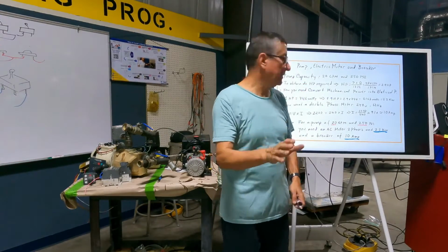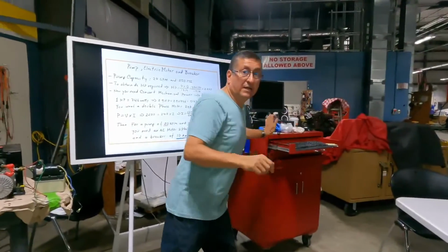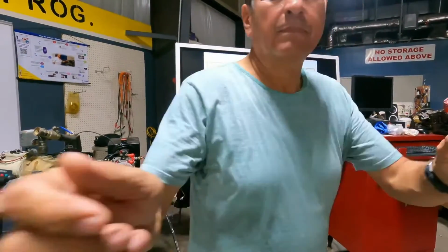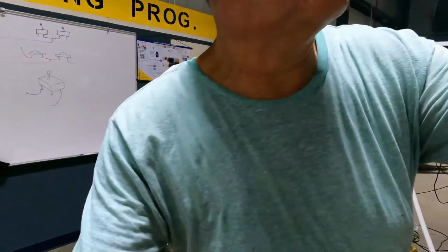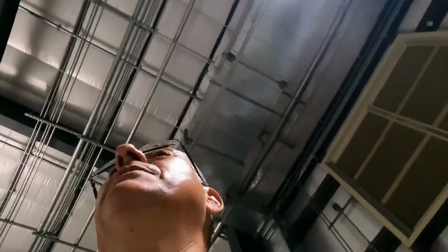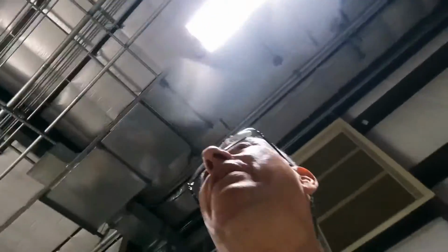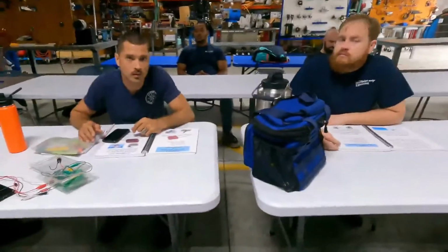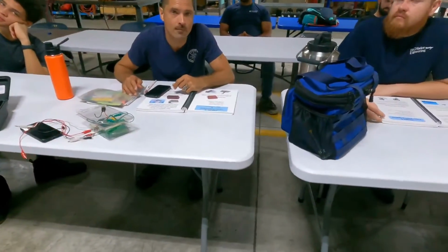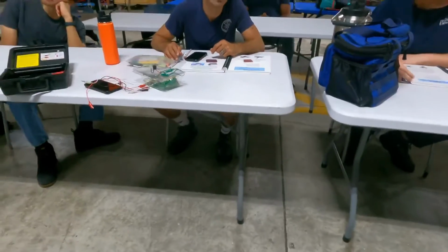All right, let me explain something. Let me show you something over there. Do elbows or bends in the fittings affect pressure? Yes, you have a drag over there. So you usually don't want 90s. You want to keep them as short as possible, as straight as possible, the pipes, the lines. This is why the recommendation is the long distance in metallic straight pipes, and only the last portion in flexible lines.